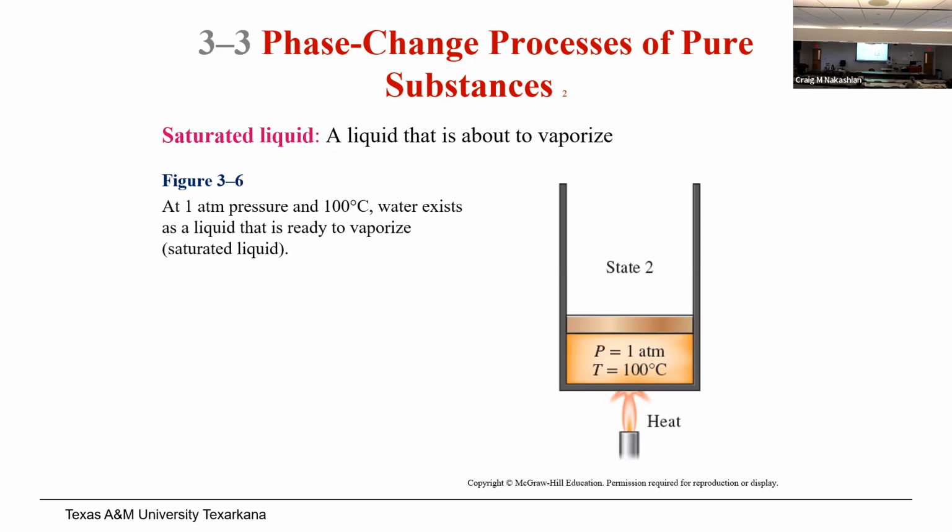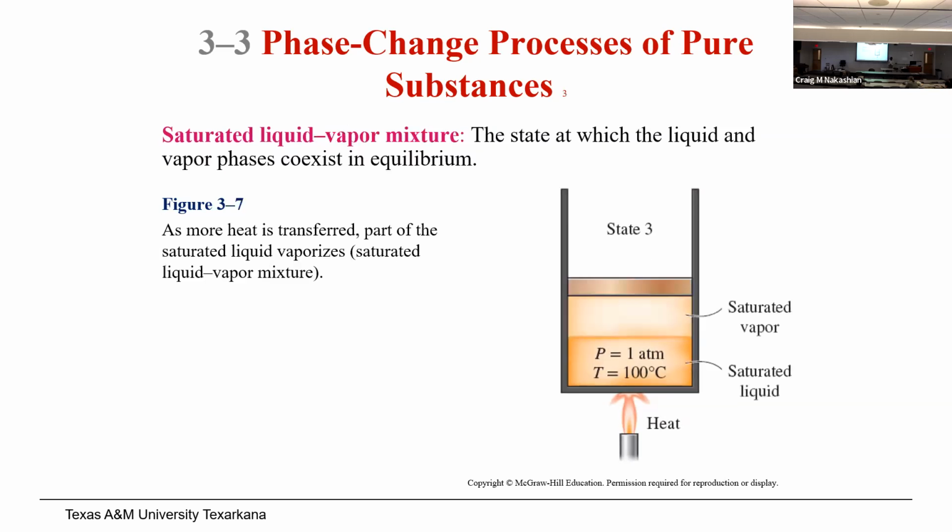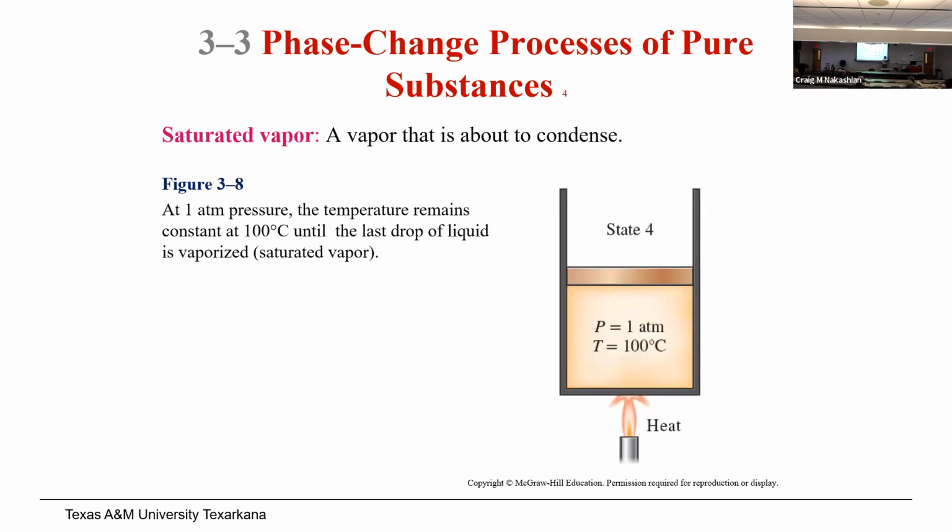And what happens at 100 centigrade? The water starts boiling. It means it will convert from liquid to gas. So it will start converting into gas, and now the volume will start increasing quite rapidly, because the gases take much more space than the liquid. And the important thing is that the pressure is always the same because the volume is increasing. And the next milestone will be when the boiling completes, and all the water now has been converted into vapor.